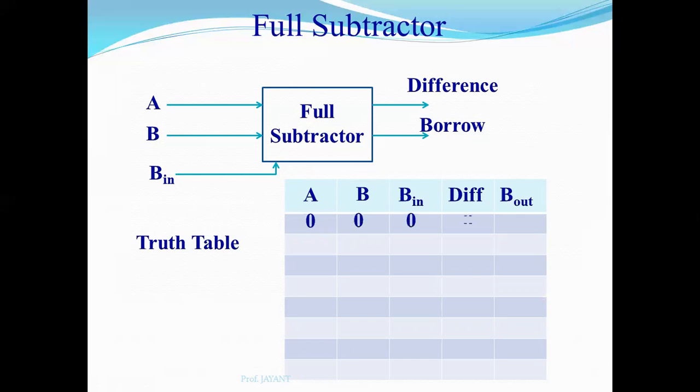0, 0, 0: the difference is 0, borrow out is 0. 0, 0, 1: 0 minus 0 is 0, and 0 minus 1 gives difference 1 and borrow out 1. 0, 1, 0: difference is 1 and borrow out is 1. 0, 1, 1: again difference 0 and borrow out 1. 1, 0, 0: difference is 1, borrow out 0.